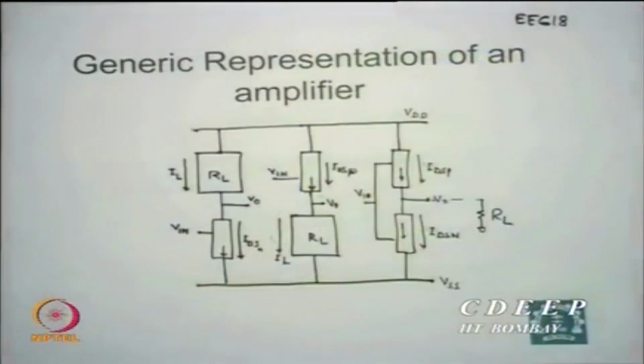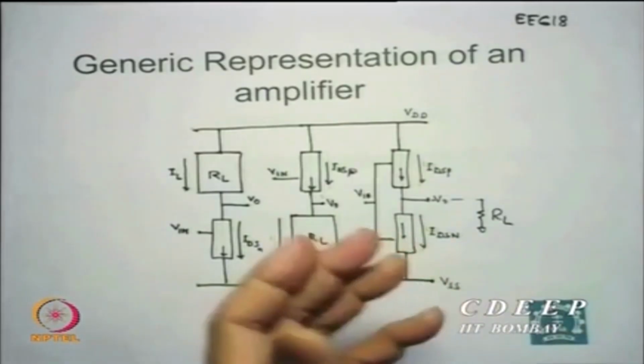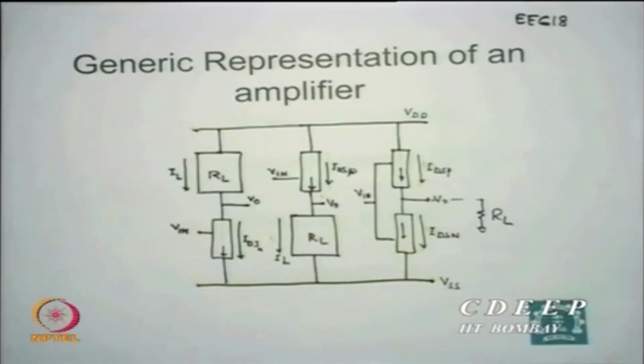In the case of normal amplifiers which you have seen just now, for example this, this load may be a resistor, but in CMOS there is no real resistor there. However, you can connect a load afterwards, so you can have something like this as an external load. But the way a circuit generally operates in an integrated circuit, there is no real resistance put any time.